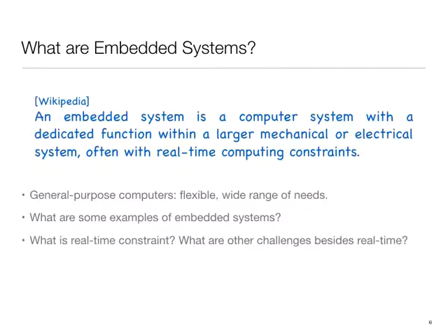What are the real-time constraints? Very loosely speaking, there are two types of real-time constraints that systems face. One is that they capture data at a certain rate, and so the processing has to keep up with it. Because if you fall behind, for example, if you have a camera observing the scene and it's capturing data with a certain amount of pixels and a certain frame rate, you just have to keep up with it, because if there is a mismatch, then you'll basically have to drop the frames. So that's a bandwidth constraint.